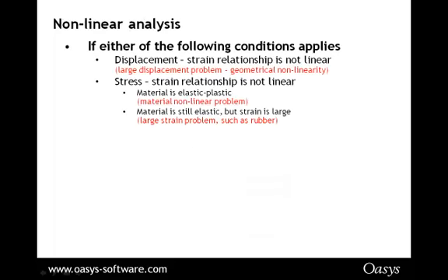On the other hand, if you're dealing with non-linear analysis, you need to look at non-linear analysis if you're getting large displacements, say flexible structures or structures exhibiting large load. I mean, imagine a cable net structure, for example. They deflect quite a lot to take up the load. Elastic plastic materials such as steel, yielding plastic hinges and so on, or alternatively materials like rubber, where you exhibit very large strain even though the materials still remain in the elastic zone.